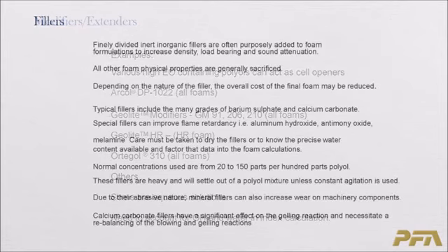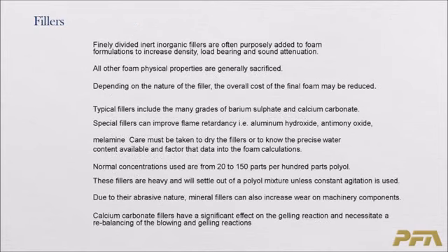Fillers are also sometimes used. If you're just using a filler like calcium carbonate, you're typically putting something like that in to make it a higher density and lower the cost. Generally, fillers hurt foam properties. There are some fire retardant fillers like aluminum hydroxide or antimony or melamine that are put in specifically to achieve fire retardant properties. Many of these fillers will affect the reactivity, so if you're either adding them in or taking them out, you need to worry and may be able to adjust your catalysis for that effect.